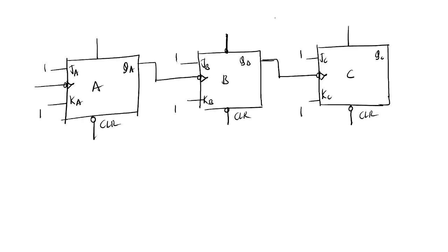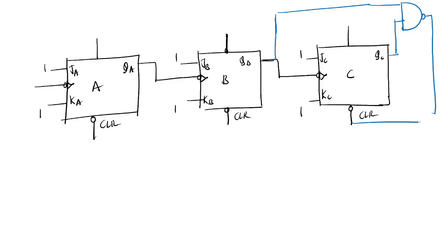Next, QB and QC are connected with the reset NAND gate, and this output is given to the clear signal. I am giving this to the clear signal. Clear means it makes the output zero, forcing it to zero irrespective of input and clock. Preset makes it one.